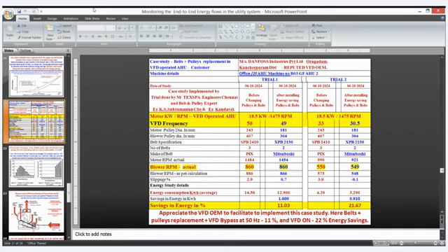All the industries are really good; they are trying to have VFDs for many of their AHUs. They are trying to operate the AHU at different Hertz for daytime and nighttime, and for summertime and wintertime, to have energy savings as well as maintain the indoor premises air quality. On the same VFD, now being winter time, this industry has gone from 33 Hertz to 30 Hertz, and they are maintaining the same blower RPM of around 550 RPM for the given blower, but they are able to achieve almost 22% energy savings.